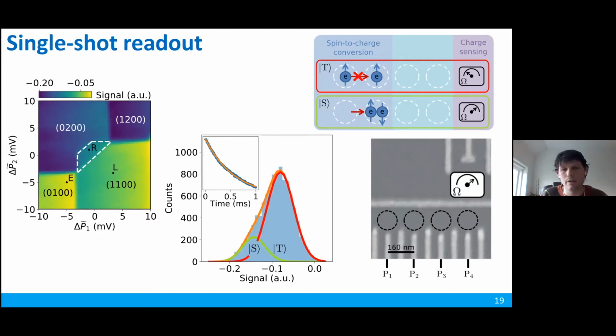What we can then plot is this nice histogram. Here we plot the readout signal for each of the repetitions, binned into this histogram. We look at the counts, and what we see is a combined histogram of the singlet signal and the triplet signal. The thing that we notice, which is what we want to improve, is that there's a strong overlap. These two peaks are hard to distinguish from each other, which in the experiment means that if you have prepared a certain qubit and you measure it, you're not really sure whether your measurement result is correct or not.